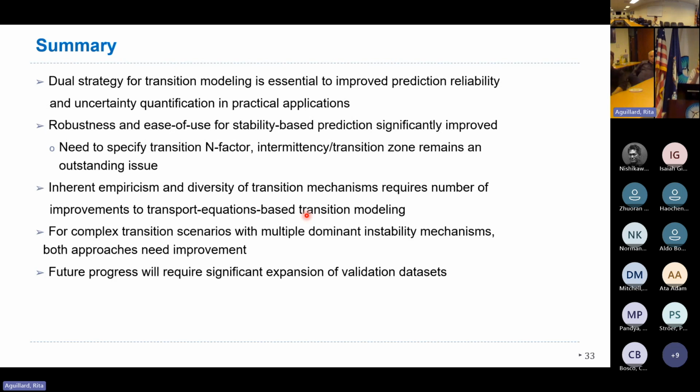Or maybe no, but then the problem is these equations don't converge so quickly. A typical fully turbulent case on the same grid would converge within, say, 10,000 or 20,000 iterations. Here I would need a minimum of 100,000. So like a 5x sometimes, depending on the problem. You have to repeat, right?